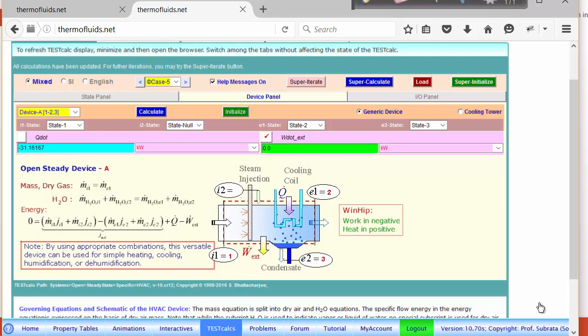But as soon as the condensation starts, suppose in a city where air is very humid, say Houston or New Orleans, when you start cooling, pretty soon the air will reach dew point temperature, and a comfortable temperature is probably below dew point temperature. As a result, moisture has to be removed as condensate, and that is a heavy penalty.